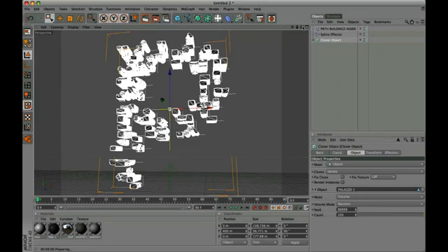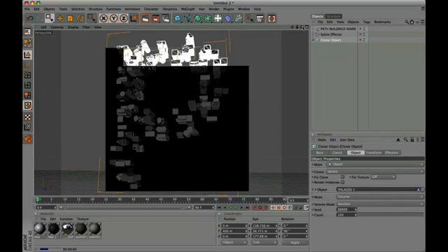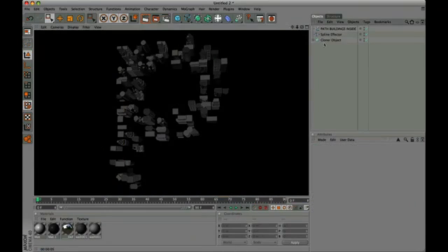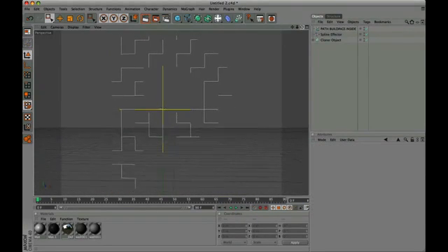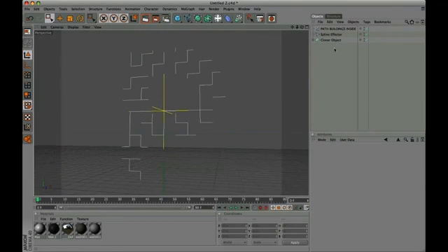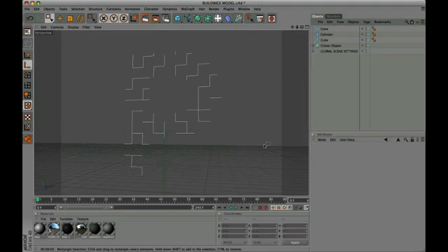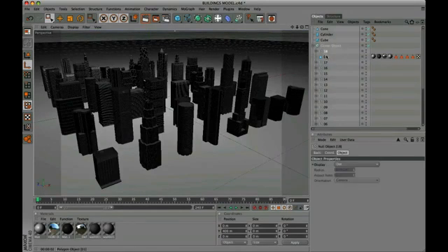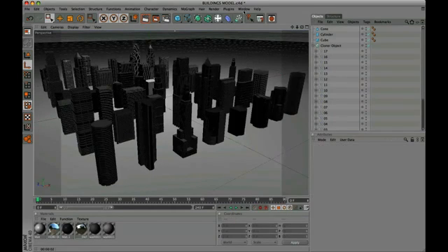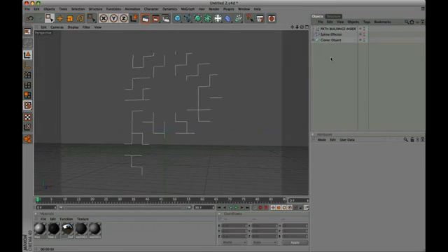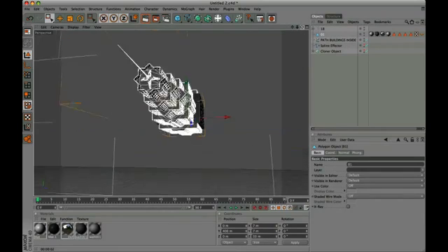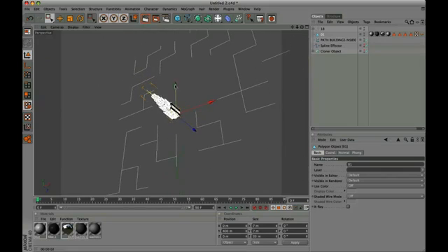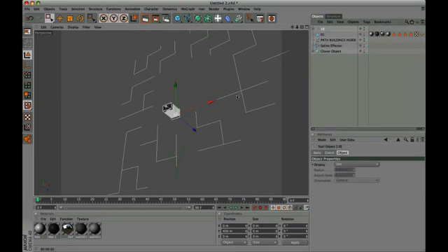We will use the MoGraph module, Cloner Object. In my project I use 20 models of skyscrapers. Okay, we begin, we import 2 models. The first model is a polygon group, the second model is a group polygons composition. The 01 model is a tower, and the 18 model is a classic building.